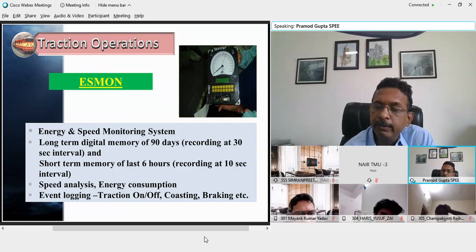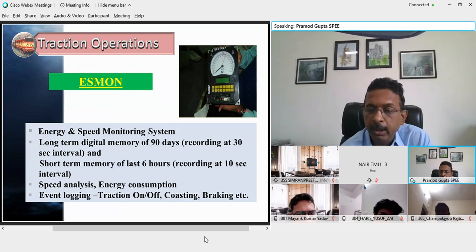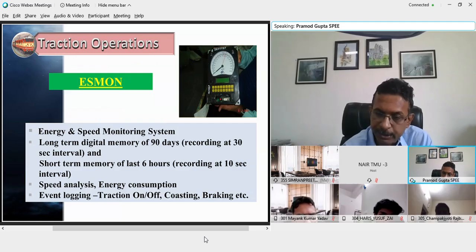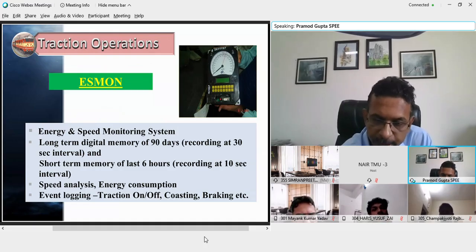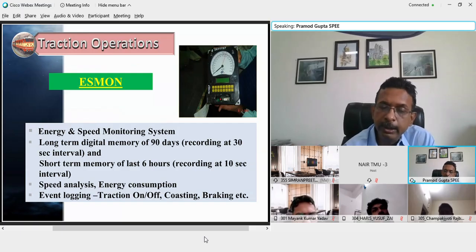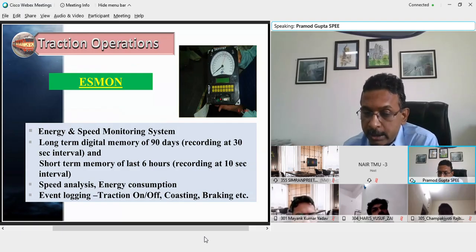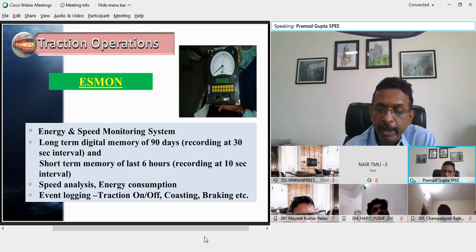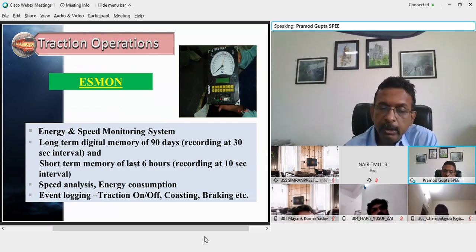The second option is the optimal solution, the appropriate driving skill, that at least should gradually reduce the speed so as to achieve 30 km/h just prior to the speed restriction area, say 100 meters or 50 meters prior to the point of speed restriction. Then we call it basic driving skill. He not only controls the speed, we don't feel jerks, and the train also does not lose time. All such actions also get recorded as to how he performed while negotiating the speed restriction.